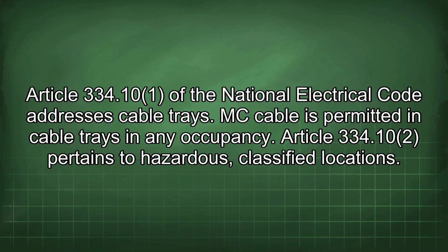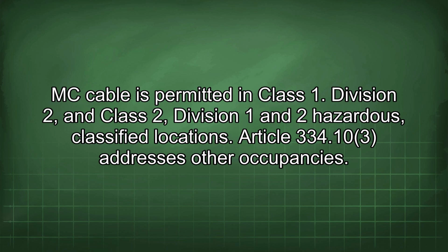334.10 pertains to hazardous classified locations. MC cable is permitted in Class 1, Division 2 and Class 2, Division 1 and 2 hazardous classified locations.